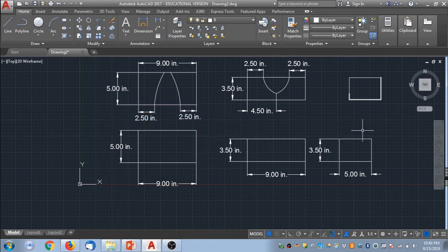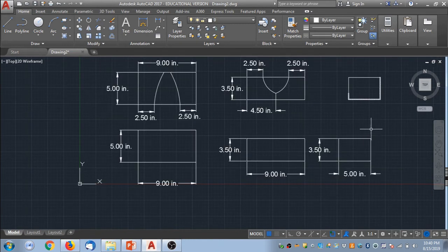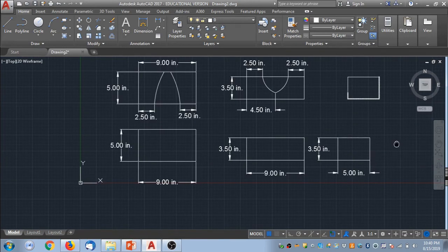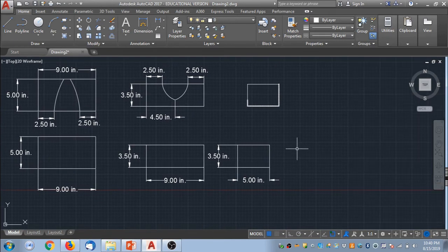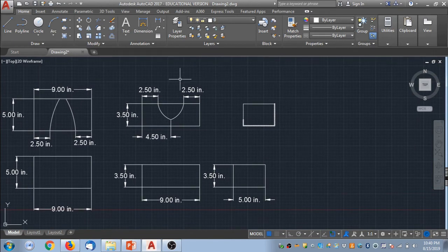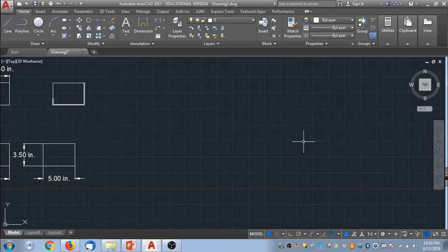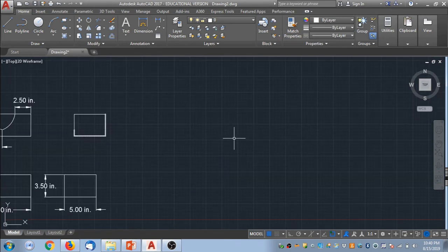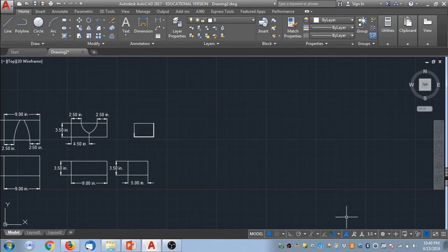So now we've got our normal views, our section cut, we've dimensioned them up. The only thing we kind of need to draw now too, as well, is our isometric drawing. And this is actually not super hard in AutoCAD because AutoCAD has an isometric drawing view. If you go down on the bottom, I'm going to scroll over to give myself some more room. It's down on the bottom right, and it looks like the crosshairs turn sideways.